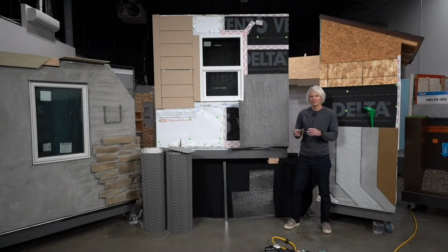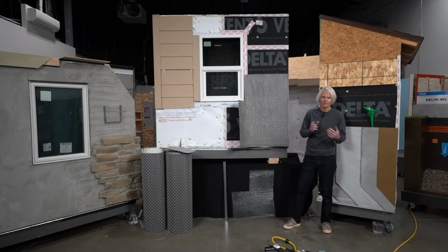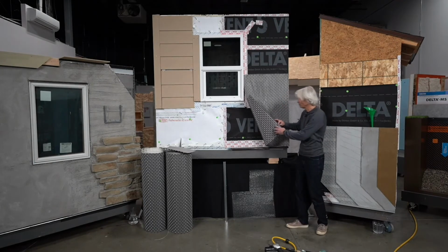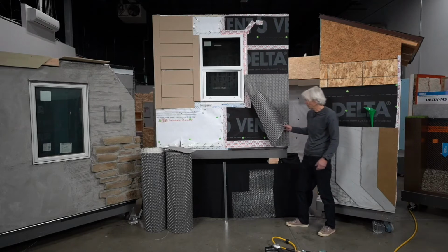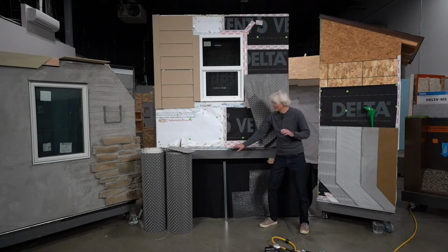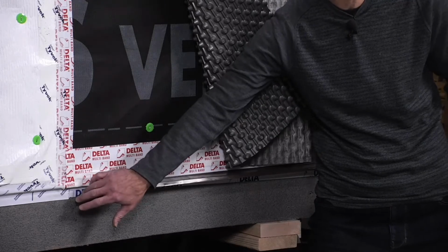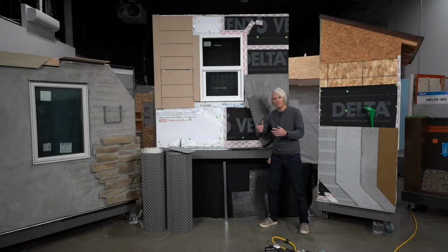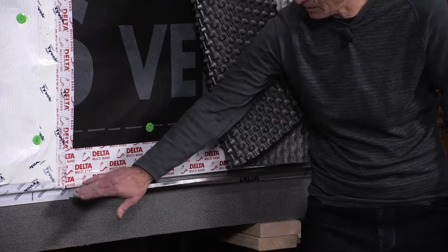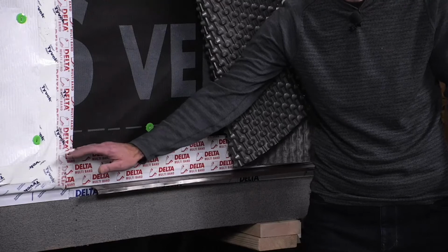So here we are in the shop to put some of these details of the test and look at a few of these product applications to put rain screens inclusive with the Stucco systems. So here's our first mock-up that we've put together. And just to go through several of the small details, the first thing, and you'll see us talk about this quite a bit at CI Live when we do water spray rack testing and other things, is that we've got a piece of flashing that's down here. And that piece of flashing was installed before the weather barrier and any of the other flashing materials. And it's a peel and stick flashing that's extended down onto this pretend foundation and then up and behind the weather barrier onto the face of the OSB wall.